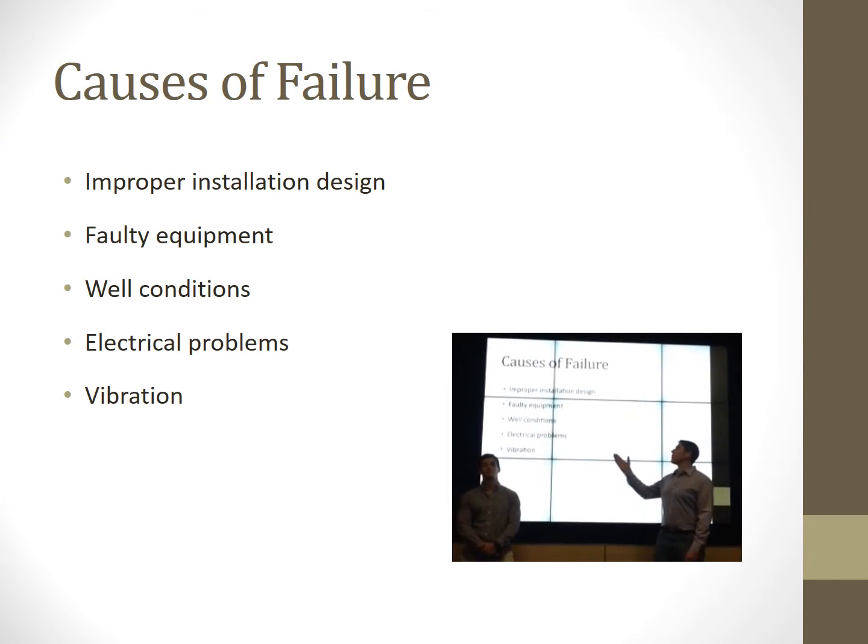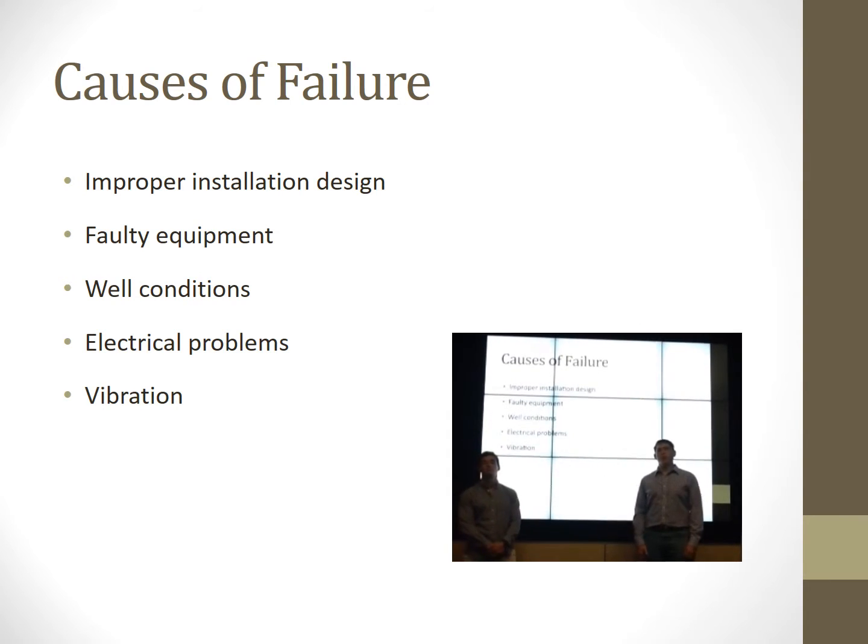These are the 5 main causes of failure for an ESP. The first one we'll talk about is improper installation design. This comes from when you don't run in between your recommended liquid flow rate range for your pump. This accelerates pump wear very fast.